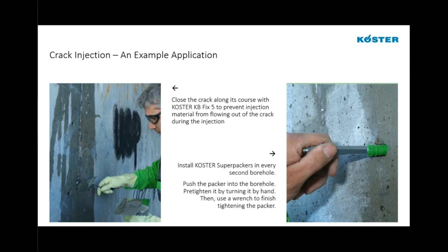Another option is, in finer cracks, we can leave that surface not sealed, and we can see the material moving up the wall in that manner. This is really a means and methods choice to make sure that we can monitor the material moving up the wall. Again, there are those two different schools of thought, primarily depending on the width of the crack as well. If the crack is very wide, we're definitely going to need to surface seal it to prevent material from flowing directly out the face of the crack.